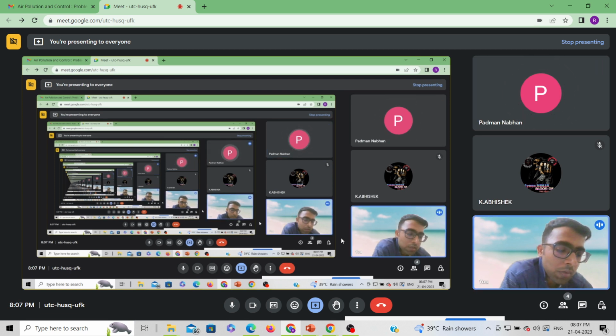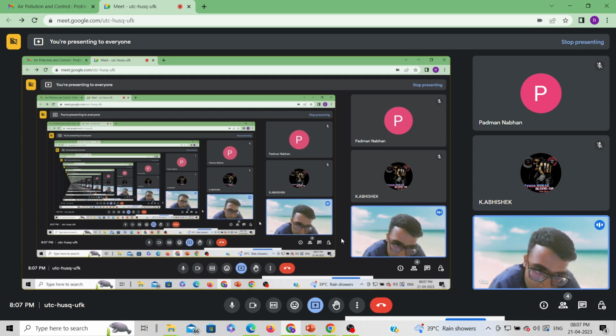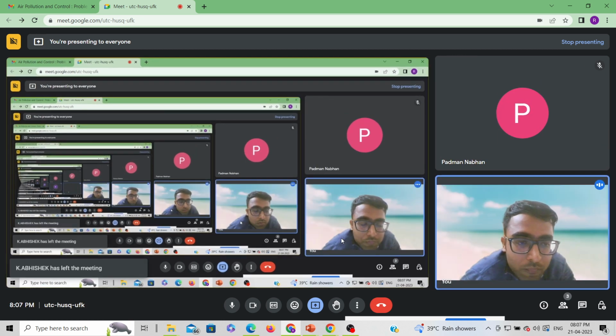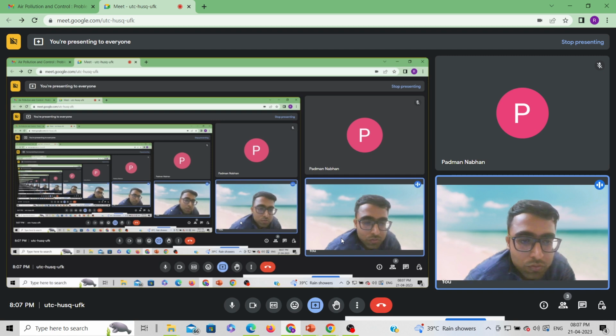In my topic, it was the biological process. I worked on different removals, based on wastewater treatment. In wastewater you will get COD, BOD, ammonia nitrogen and nitrate nitrogen. So you have to calculate the removal efficiency, for example for a reactor you are designing, how much efficiency that reactor is giving. There are colorimetry methods to find out the concentration.